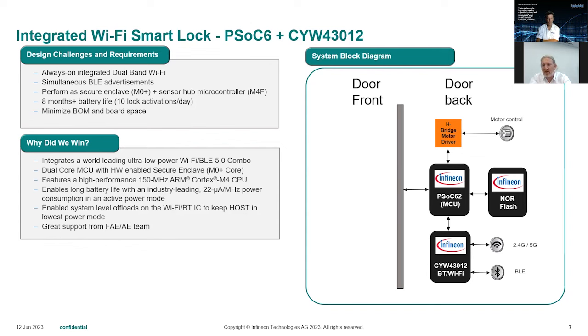So later this year, the big brother of this 43012, because these types of smart home devices spend 99% of their time in sleep mode, waiting for somebody to come and use them. So what we've done is we've minimized the sleep retention, the sleep current in these devices to double again the battery life of the smart lock by really examining what we keep alive, what is active during these sleep modes, but at the same time allowing the lock to wake up in a fast enough time to respond to an asynchronous access.